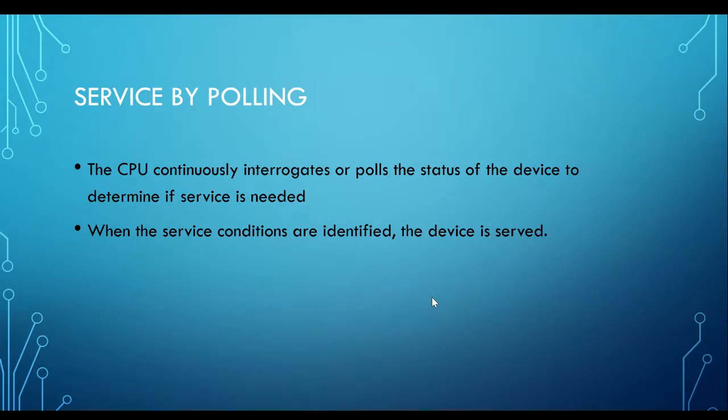Okay, the first and most obvious way of doing it is by using a polling system. It means the computer keeps on checking the status of the keyboard. Maybe you have a register. When there is new information, a flag is raised. It could be one of the registers. So when the flag is raised, this is where you can use the polling system. Polling means you check the register value every computer cycle. Let's say, for example, your main program consists of a lot of stuff.